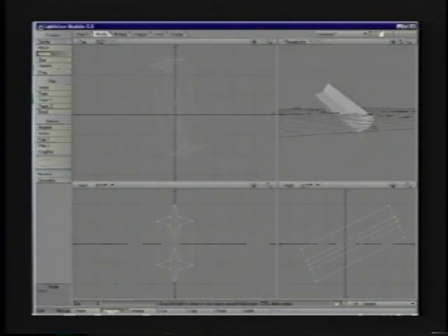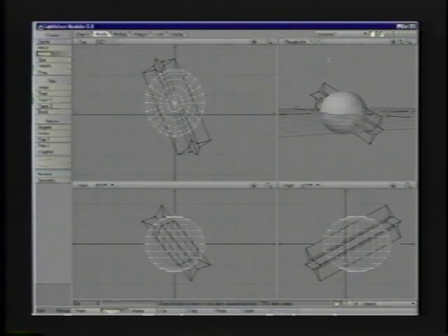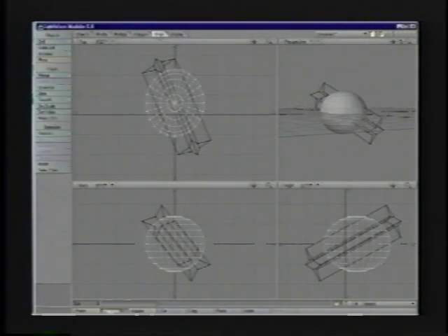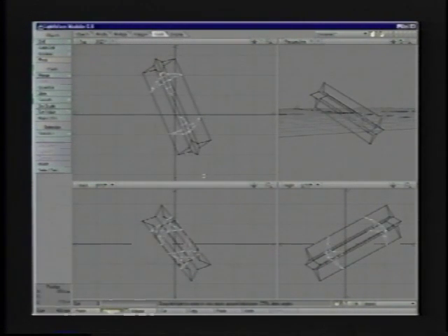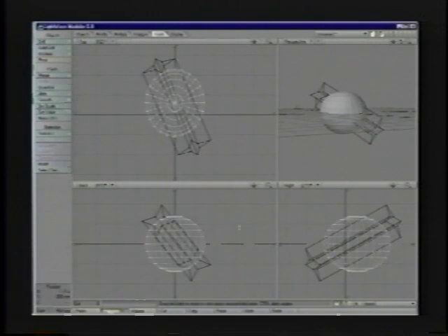And now I'm going to rotate this star around. I have the power to do exactly what I did before, but along an arbitrary axis. So if I just go in here and rotate my three-dimensional cutter, we'll leave that in the background. Now if we go back to Tools, Solid Drill, Core, you'll see it does exactly the same things, except it allows me to do it along this arbitrary axis.